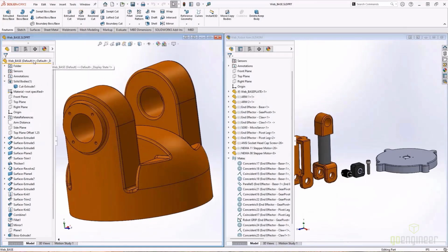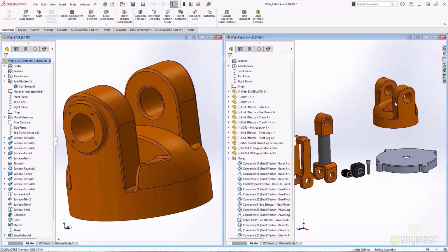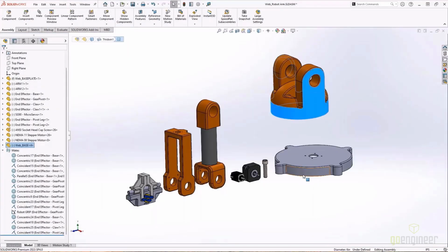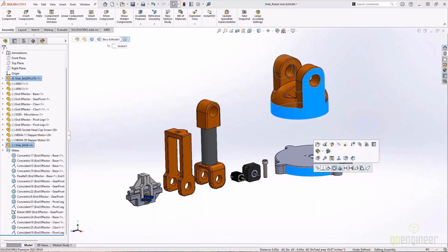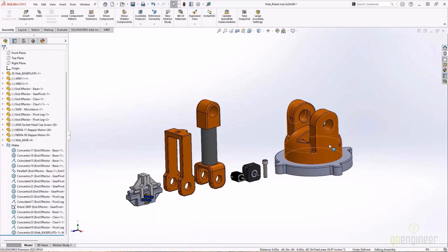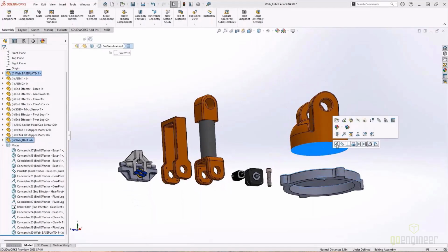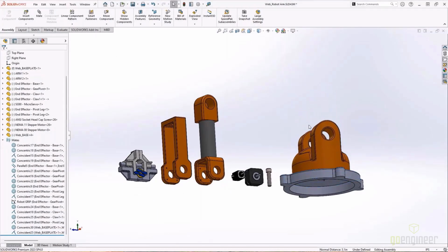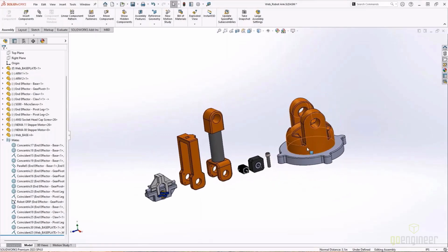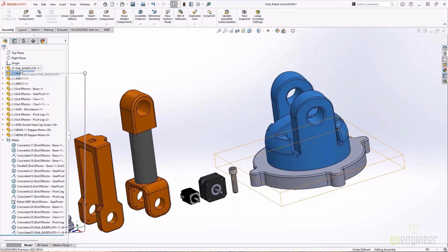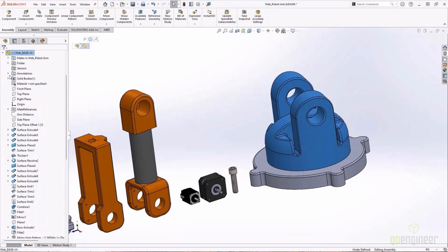Let's go ahead and tile. I'm going to drag and drop that guy into the assembly. I'll go ahead and close out of the part and maximize the assembly window. And we're just going to use some mates. So I'm going to pick on the 2 cylindrical faces, make a concentric mate, and then pick on the face, hold down Control, and then that's when the little dialog will pop up, and we'll do coincident there. All right, so that thing can now, all it can do is rotate now. Let me go and reorganize that in the browser tree. I like that to be nice and straight.